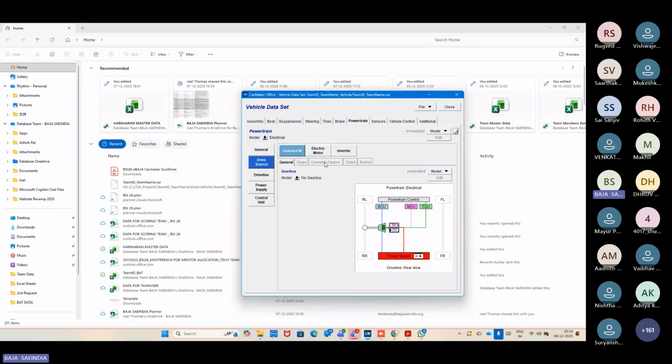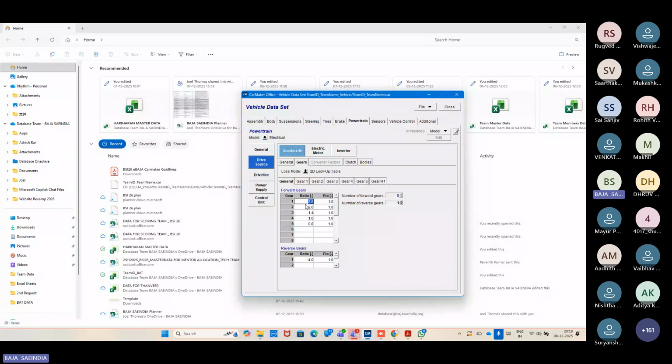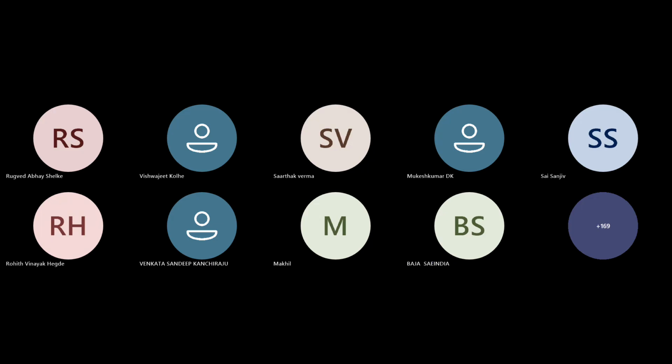For the powertrain of electric section, you are having a continuous variable option as well. But in case it is not working well, you can use this automatic manual transmission. Then start putting low values of gear ratio, like 0.1, 0.2, 0.3, and then go on. That will help you with parameterizing this CVT. Reach out to us if you still have any queries.